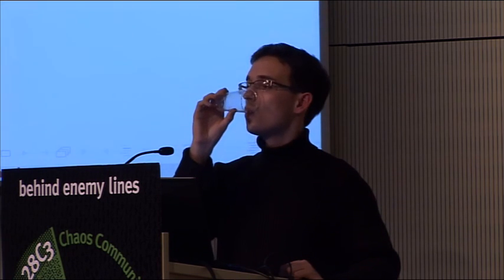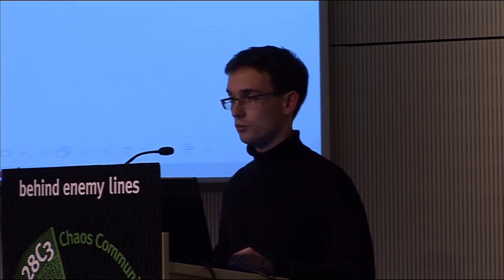Yeah, but for example, you can hook up debuggers from Lauterbach or other companies who make debuggers, and then you can just debug via JTAG. It's a normal way to debug a device. You have the trace cell that is connected to JTAG inside the chip, and then you can debug with a JTAG debugger. And so if you messed up everything, you can just write the flash again. Yeah. But I don't know, honestly. I have not tried to reflash the device for the moment. As you saw, I'm just pushing the code in the RAM at runtime.